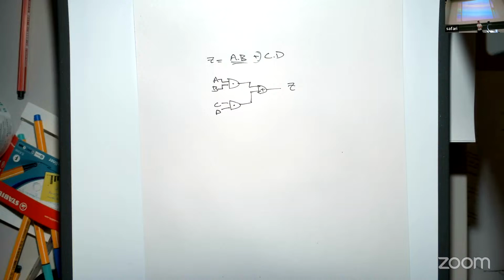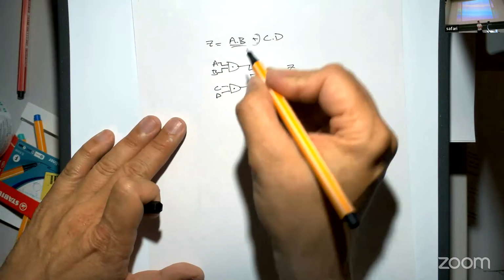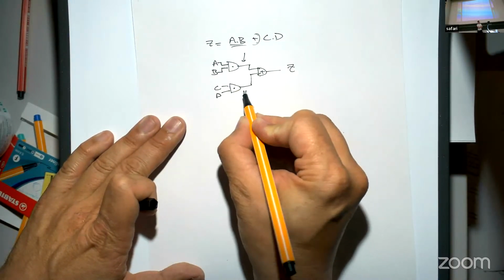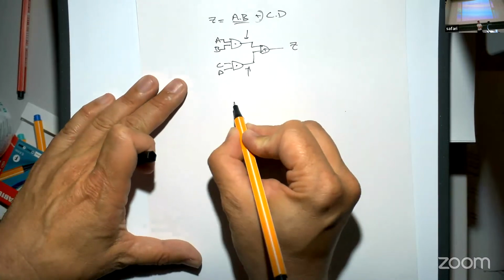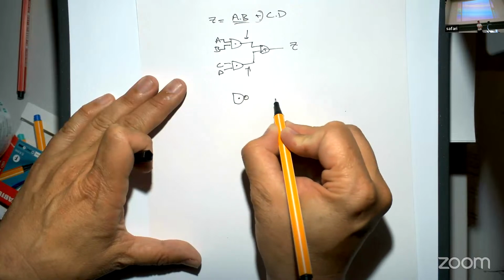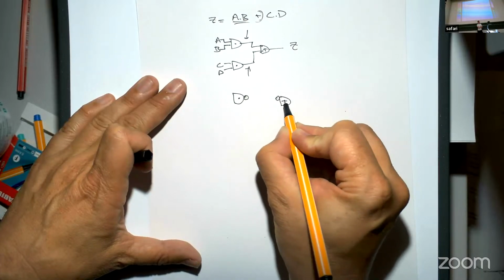The double negate, like globally, and then we use De Morgan to make them equal. Yeah, so that's actually a nice trick. So what your colleague says, we double negate, let's say, these outputs here. So instead of having this, we have the AND gate, we invert it, and then we invert the input of the OR gate.